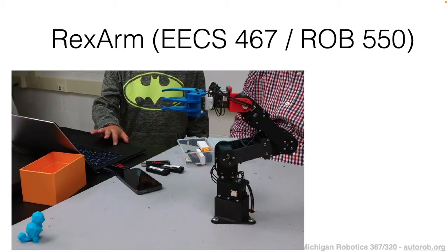using the foundations that we're building on in this current course. This particular Rexarm robot is a 4 degree of freedom robot, and we can apply some of the techniques that we talked about today for finding closed form inverse kinematic solutions to this 4 degree of freedom system. We started with looking at 1 degree of freedom pendulum inverse kinematics, then we moved to 2 degrees of freedom, then we briefly looked at 3 degrees of freedom, and now we're on 4 degrees of freedom. So let's look at how this system could have a solution in a closed form,